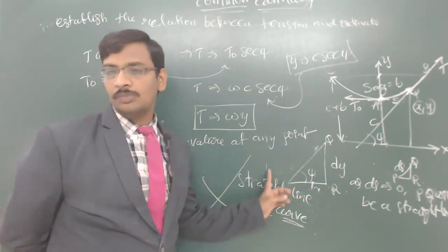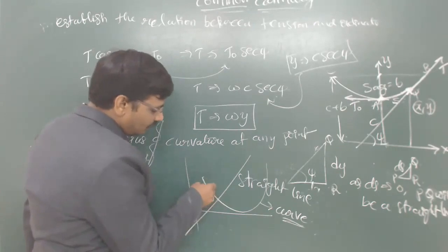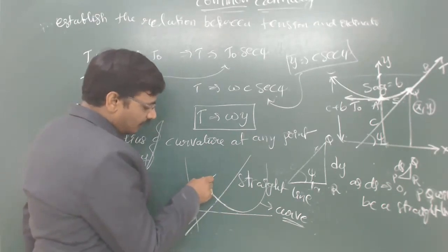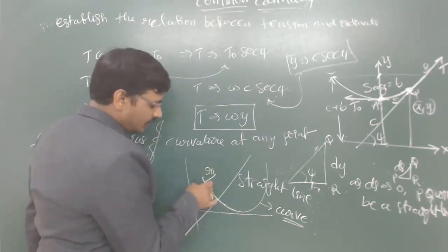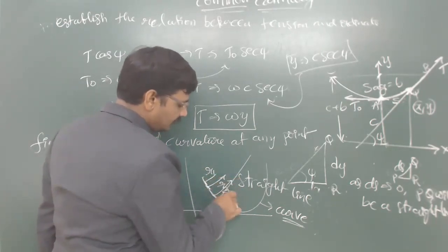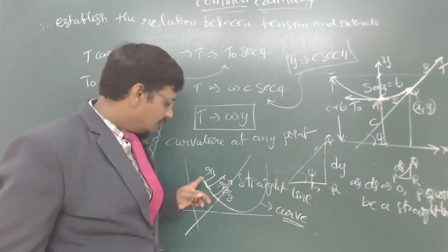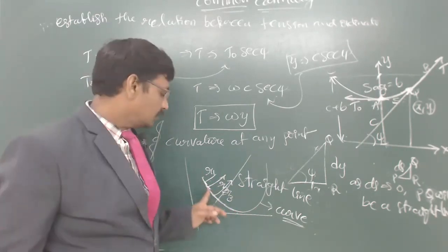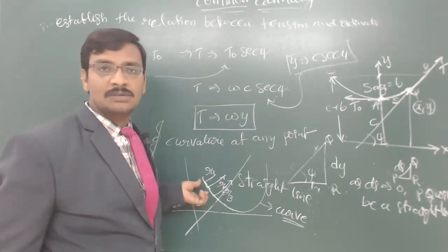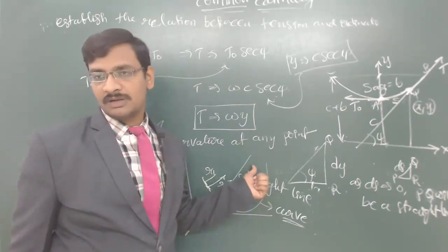So this variable slope, the way we construct this particular curve is, if you divide this part into infinitely small parts, each part is a curve of radius of a certain value. So this is R1, this is R2, and this is R3. Like this there are different radius values which you can use to draw these curves at infinitely small scale. Got it? So each elemental part of this curve is constructed by a radius, but this radius will be continuously changing at every point of the curve.